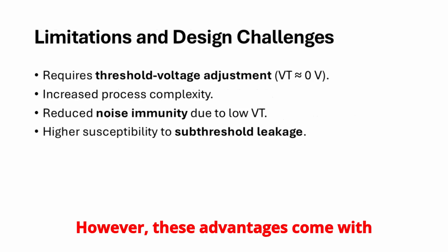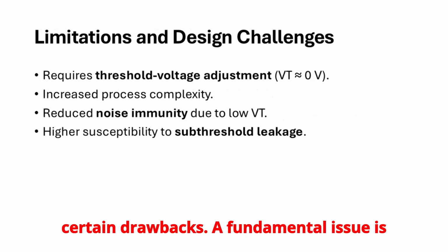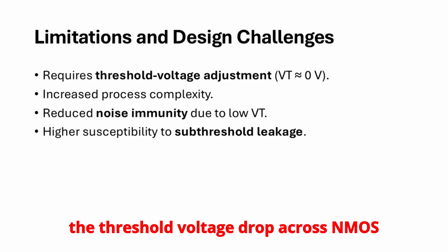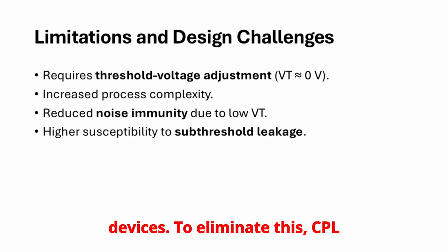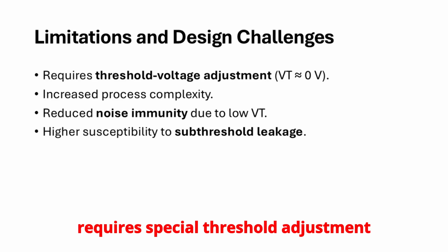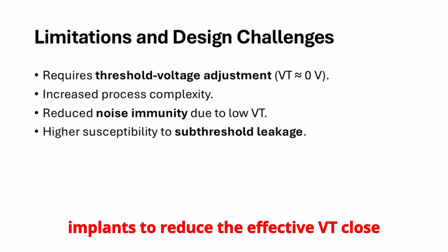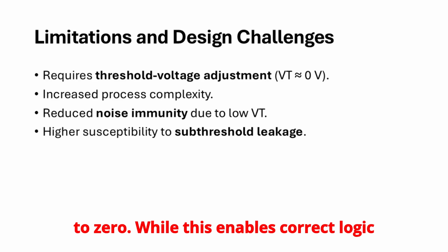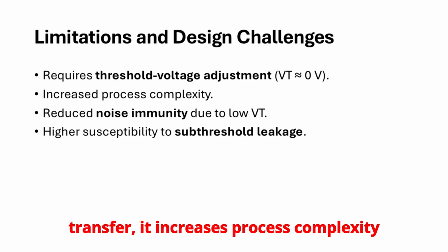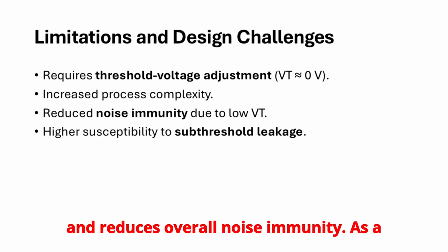However, these advantages come with certain drawbacks. A fundamental issue is the threshold voltage drop across NMOS devices. To eliminate this, CPL requires special threshold adjustment implants to reduce the effective VT close to zero. While this enables correct logic transfer, it increases process complexity and reduces overall noise immunity.